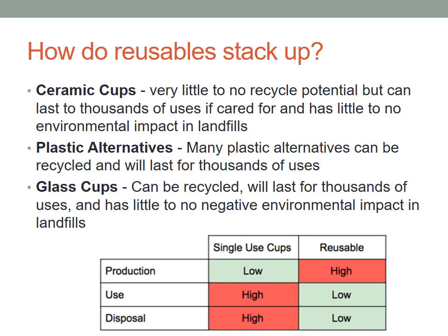So how do all our options stack up when we compare them for end of life? You might have noticed that ceramic is not coming out too well across this. It takes way more energy in its start use, and it is actually often more brittle than tempered glass. It also has poorer thermal conductivity than tempered glass. So ceramic, while it can be stylish, it looks very nice, and from a marketing point of view it's pretty cool, it's actually a poor material choice for this type of application.